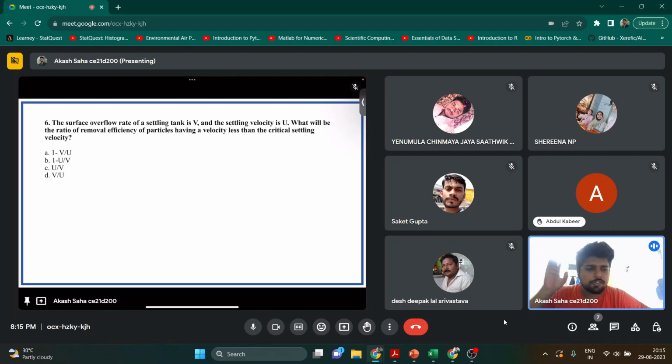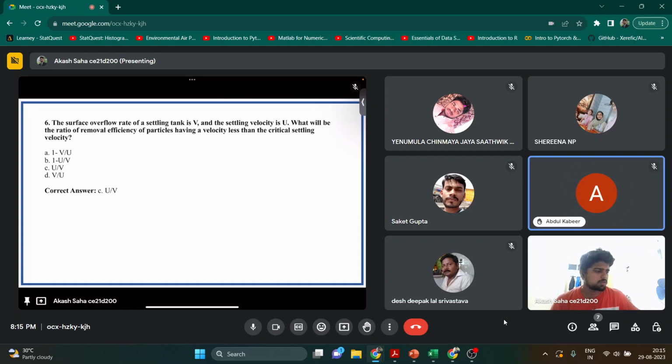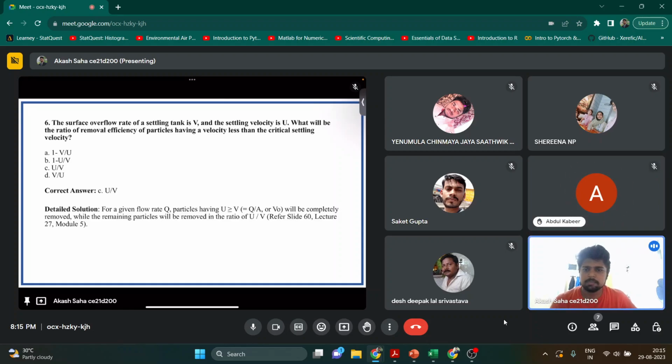So my surface overflow rate is V, the settling velocity is U. Settling velocity by surface overflow rate. So the option will be C. C option is correct. That is U by V. Others, is it clear for you? Yes, sir. Okay. So it's pretty simple, but it will be U by V.